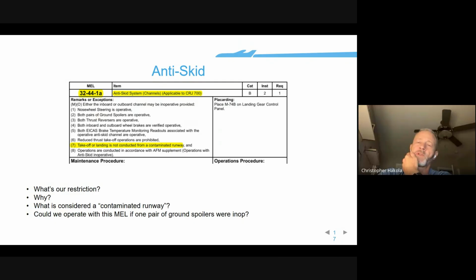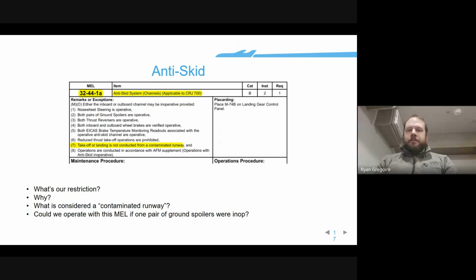Hey, Ryan, does that include stuff like rubber at the approach end of the runway or sand, stuff like that? The contaminants? If it's greater than 25%, it covers it, okay. Yep. And then for the 1/8 of an inch, that's specifically for water coverage, like water, snow, slush, dry snow, wet snow, compacted snow, sand, dust, marbles, whatever it happens to be.